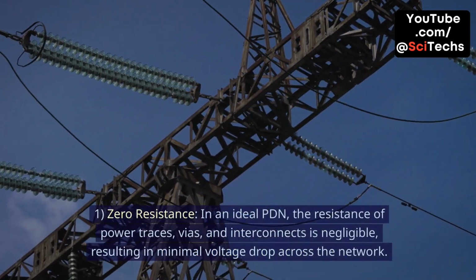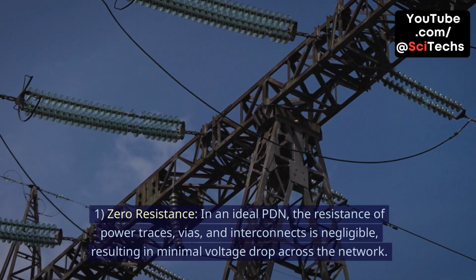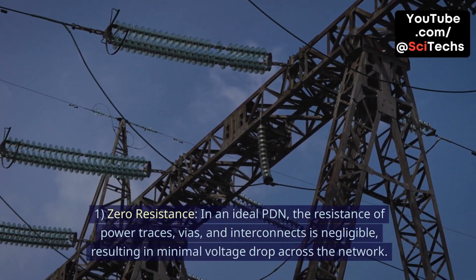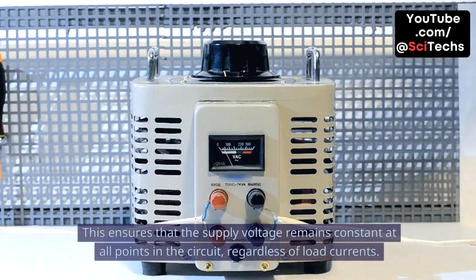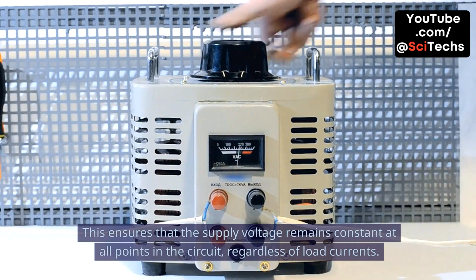1. Zero resistance. In an ideal PDN, the resistance of power traces, vias, and interconnects is negligible, resulting in minimal voltage drop across the network. This ensures that the supply voltage remains constant at all points in the circuit, regardless of load currents.